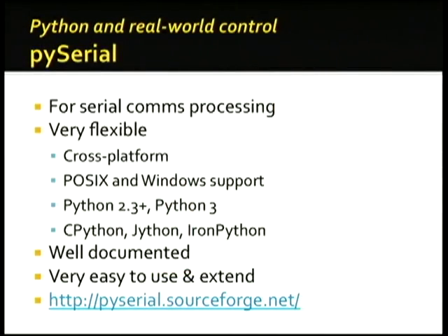That's right. Once you've actually got a board, how do you talk to it? One of the best ways is, if it has a USB interface, USB to serial converter, and then just use Pi serial. The advantage of it is it just works. It works on a Mac, it works on Linux, it works on your Unix boxes, works on Windows. If you've got a POSIX compliant operating system, it will work, and it will work on Windows as well.